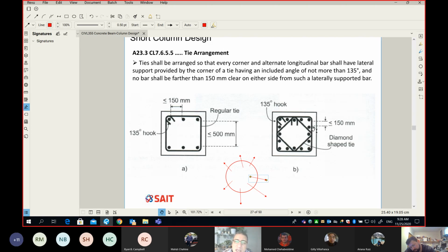Okay, same thing here. So with this discussion, please understand it applies to square or rectangular columns, not to a circular column. Because in a circular column, as I said, the tie will have a pure tension force, and it's fantastic. It's going to do it. It will confine all the rebar. However, let me take you through this problem here.